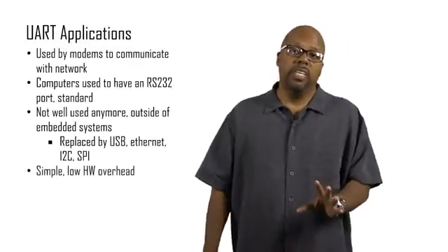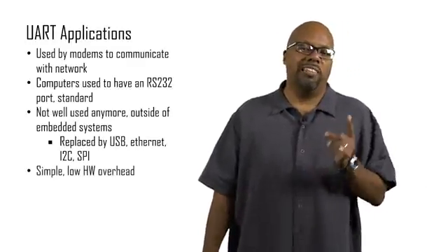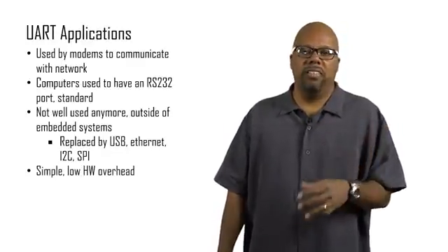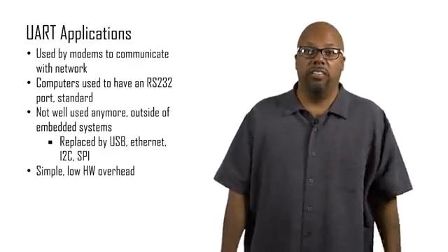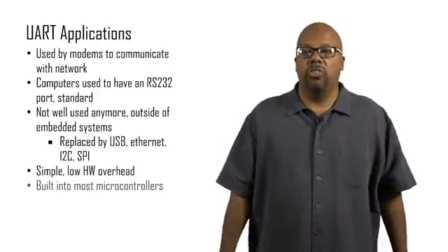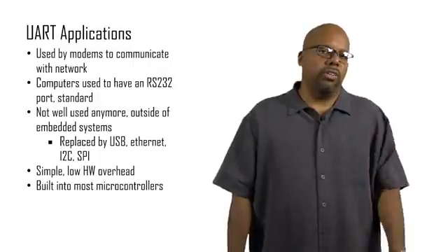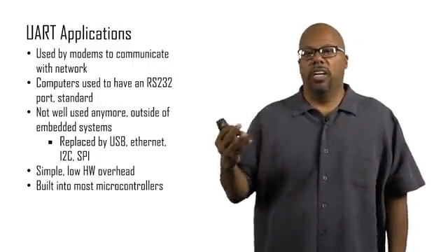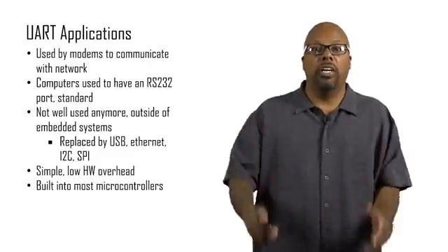But UART is a very simple protocol, and it's low hardware overhead. That's another reason why people still use it in embedded systems for communication, for debugging, and things like that. It's just so convenient to use, and it's built into most microcontrollers. Most microcontrollers have hardware support for UART, so why not use that for debugging?